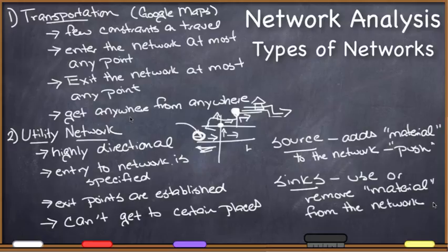So you can begin to automate that, but as it is with all of these things, if you automate the creation, you may be missing a lot. So maybe the automated creation of this based just on sources and sinks is the first step, but then you go back and you revise your network and you create your data set so that it's much more explicit about the directionality of every edge and every junction, and it much more accurately represents the thing that you are trying to model. But sources and sinks are very important terms to remember when you're doing utility networks.